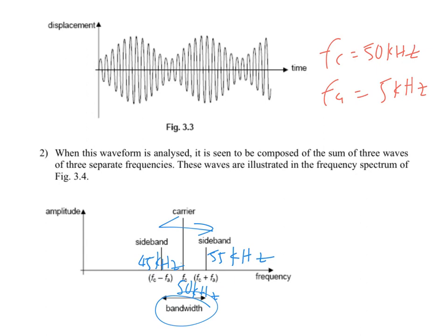Do you understand? And the 2 waves here, they call it the sideband. So you need to know the names. This is called carrier. This is called sideband. The 2 sidebands will have lower amplitude than the carrier wave. How much lower? It's about 1/3 of this amplitude. So around 1/3 when you draw the sidebands.